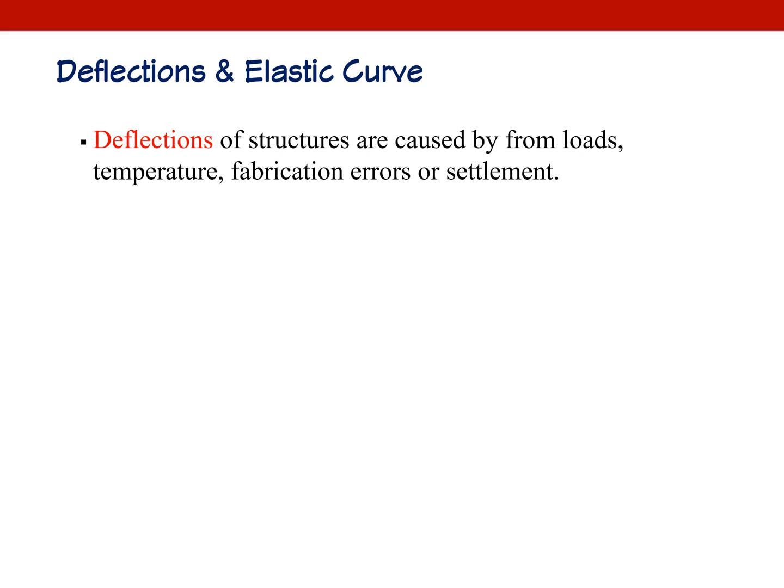Deflection of structures is mainly caused by loads. And sometimes, if temperature fluctuates, it may cause stress and resulting deflection. If there is a fabrication error, deflection may occur. Or settlement of foundation may cause deflection.